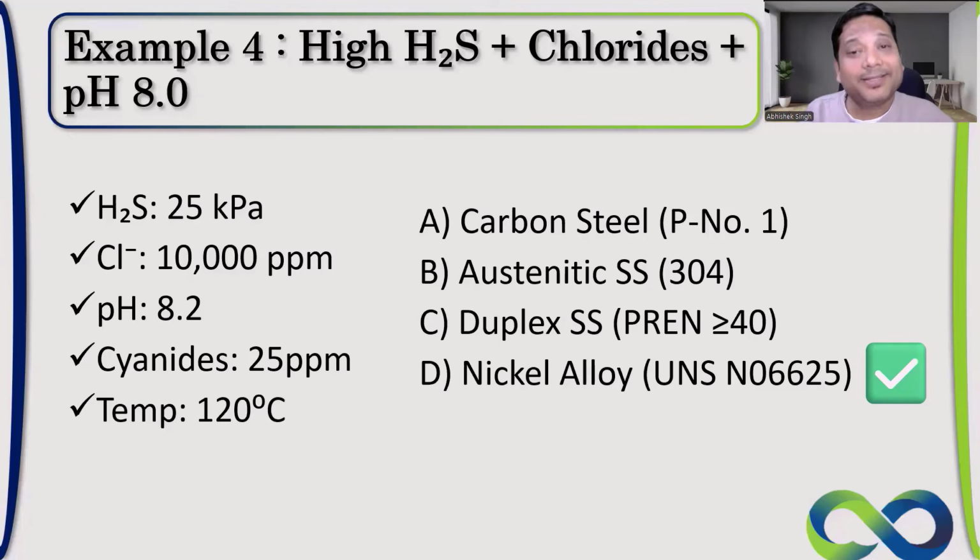For refinery services where NACE 103 is applicable, there is no history of HIC, or maybe you can say that there is no data available for HIC. So NACE only talks about SSC. Okay. So there is no standard developed for HIC for refinery services. So it is not available.